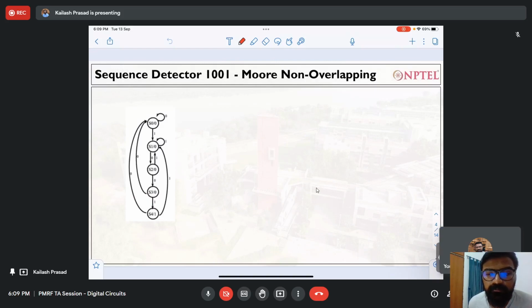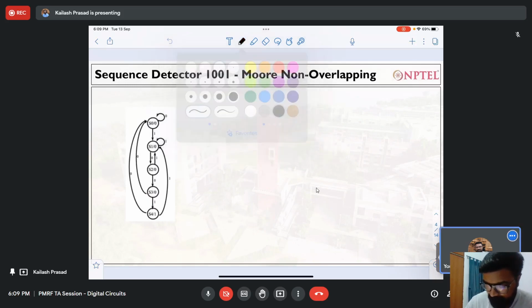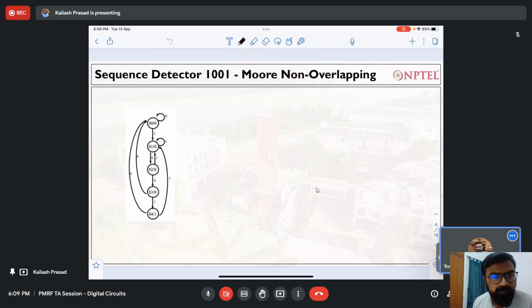The Moore machine is based only on the present state, and the Mealy machine is based on the state as well as the input. Okay. Any comment on the number of states that will be required for a Mealy machine and a Moore machine? If I want to detect an n-bit sequence, how many states will be required for a Mealy machine and a Moore machine? N states, obviously. Sorry, n states for both.